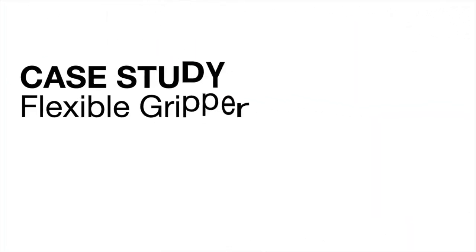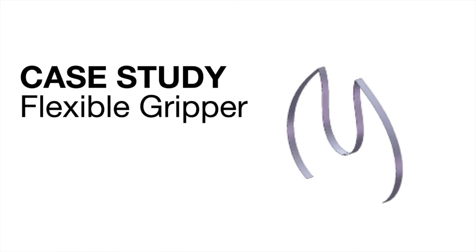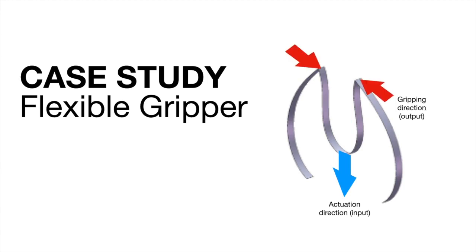Okay, ready? For our first case study, we are going to simulate the mechanics of a flexible gripper. This is how the flexible gripper looks. When the gripper is actuated at this particular point in this downward direction, correspondingly the gripper will create a gripping effect at this upper end point here. For this simulation, we are going to assume the two ends here to be rigid points, as in they don't move.